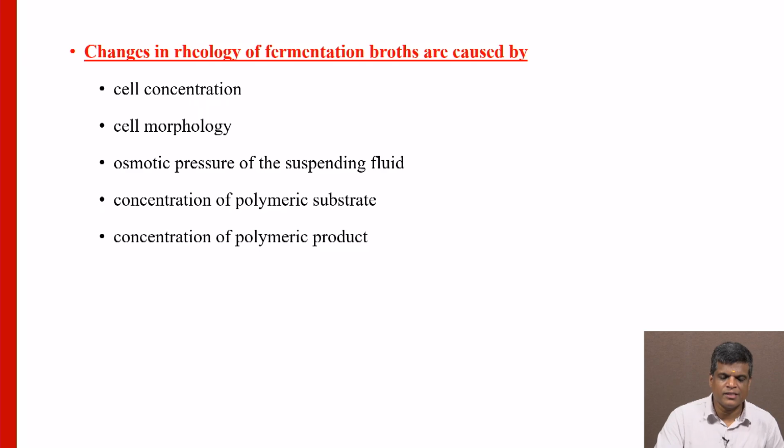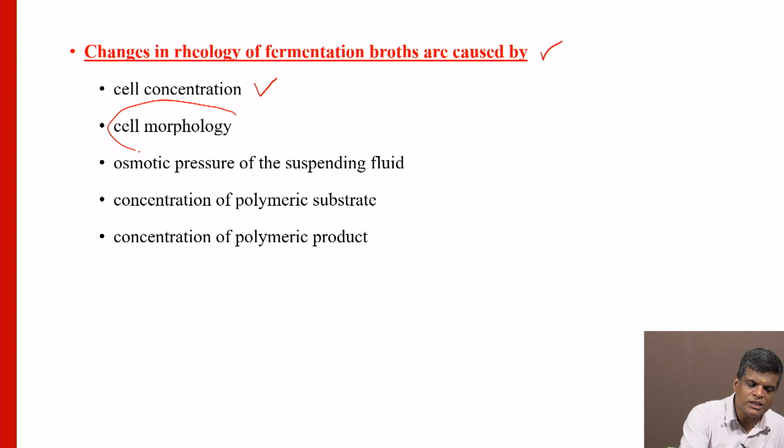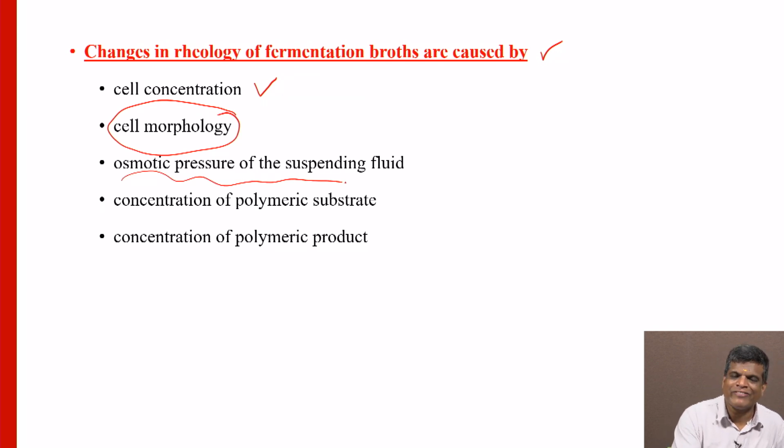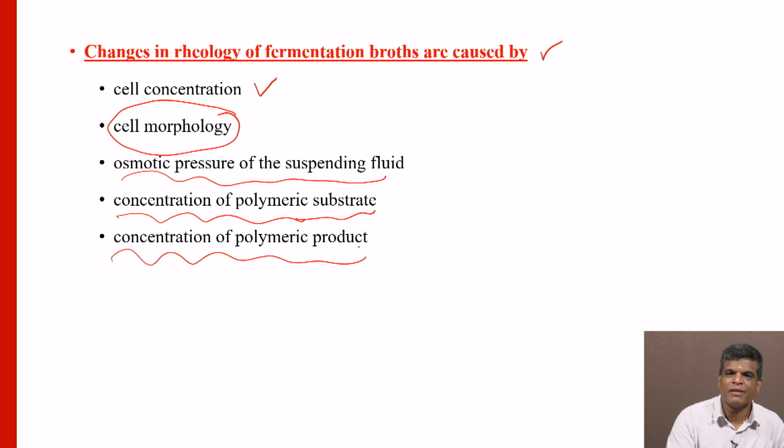What are the changes in the rheology of the fermentation broth caused by? Definitely the cell concentration is the main factor. Then the cell morphology, next the osmotic pressure of the suspending fluid, then the concentration of polymeric substrate, and finally the concentration of polymeric product. These are the factors that change the rheology of the fermentation broth.